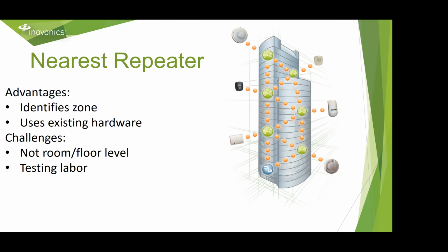to a repeater, but what it would do is it would hear an unrepeated or first hop alarm signal. And then what it would do is transmit an extended length message heard by the software-based senior living head end. And that message was the pendant ID as well as its ID. And in order to dial down the defined location area, there was a potentiometer or a pot on there, and you could turn it so that you could essentially affect its hearing.